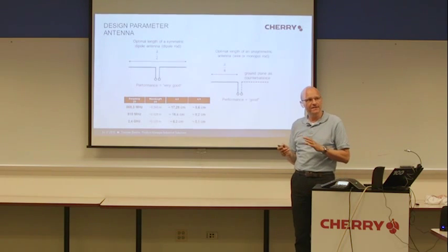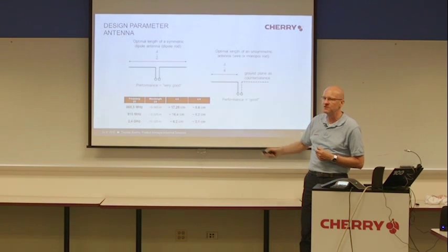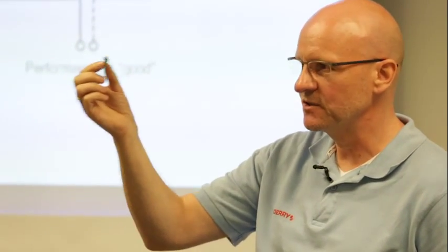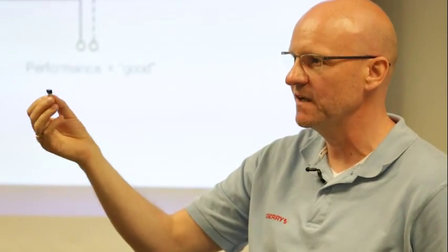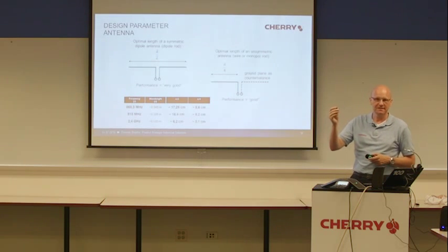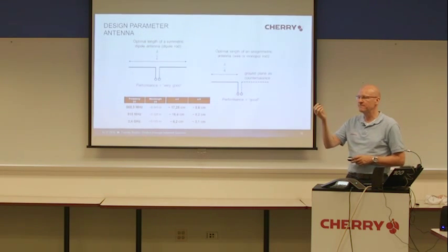And this is, for example, another advantage of using 2.4 gigahertz, because the antenna design can be much shorter. This is the reason why it's currently possible to use 2.4 gigahertz systems with such receivers, because there are very, very small antennas inside. No wiring antennas. These are chip antennas or SMD antennas placed directly on the SMD. The performance of a 2.4 gigahertz antenna on such a small receiver is much better than when you would use the 868 or 950 megahertz frequency. That is another advantage: the antenna design can be more adapted to small housings.